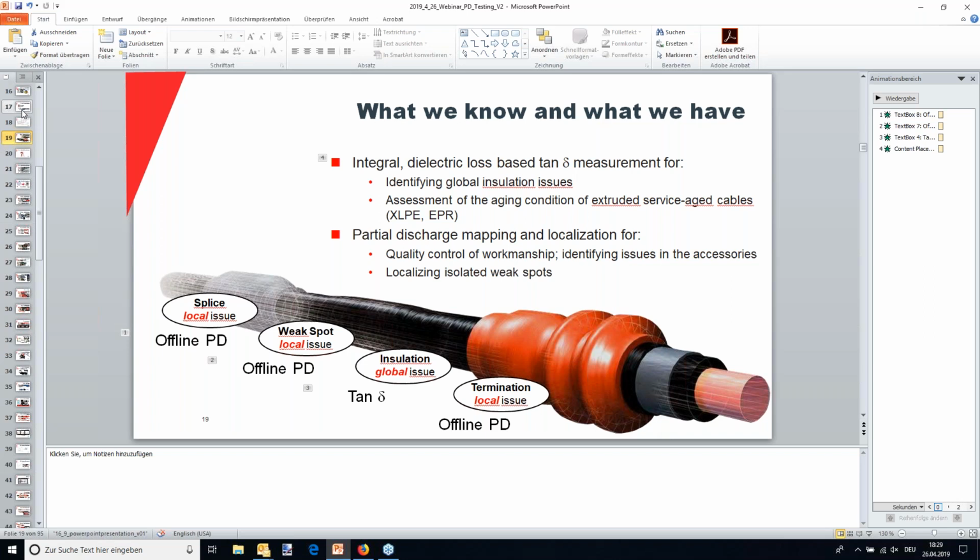So when PD occurs in a cable, that is a whole different animal than when it occurs in some other substation assets. We have solutions for monitoring medium voltage switchgear, the product called PD Scan. And for high voltage transmission environments, let's say the high voltage end terminations, there's the UHF detector, so the non-conventional measurements. But that is more like substation monitoring or substation testing. On cable, that is a whole different animal in terms of PD.